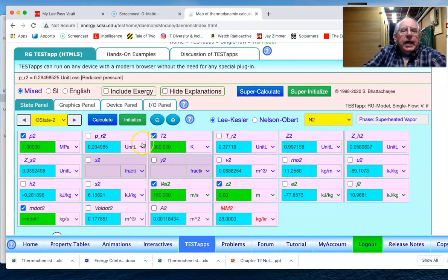And so we see that at that particular temperature, it is, again, above the critical temperature because we know this particular substance is cryogenic in nature, and so the dome would only appear at very low temperatures. And so we have our kinetic energy, our temperature, our pressure and our m dot, and we see in this particular case that it's very close to behaving as an ideal gas. It's 0.997 for the compressibility factor.